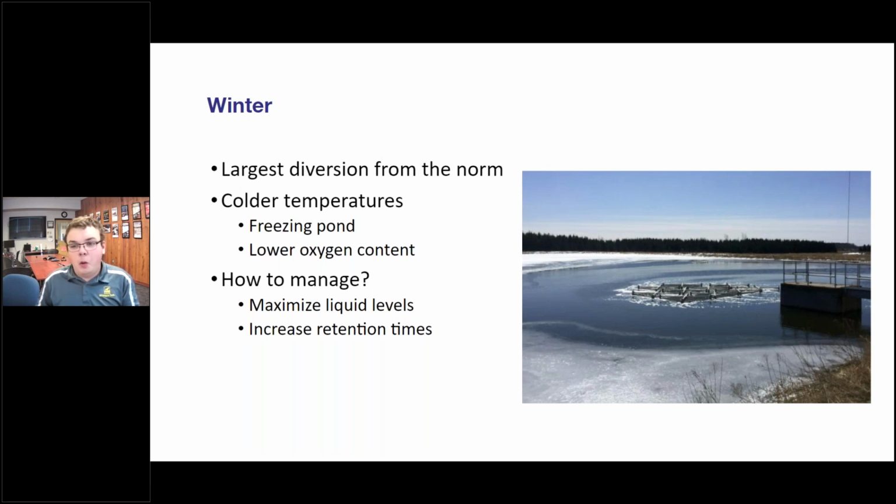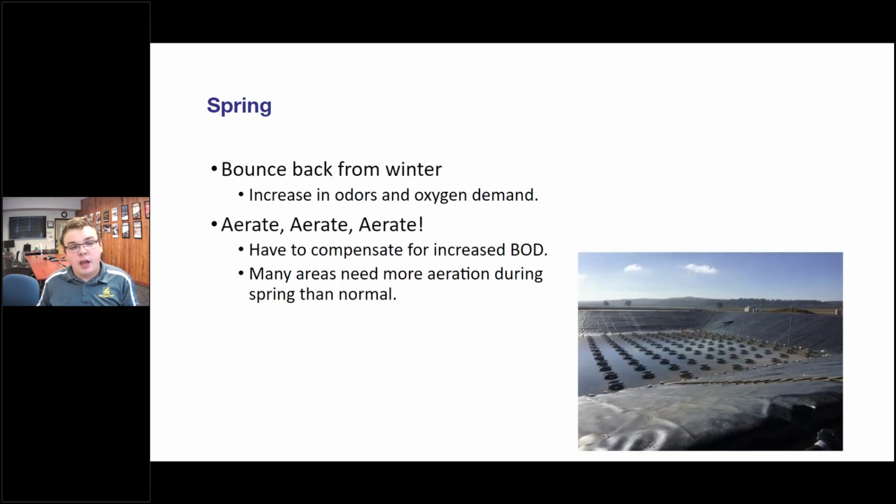Eventually, once spring hits, you're going to have this huge bounce back from wintertime. You're going to have an increase in odors and an increase in oxygen demand, because all of this waste that's been sitting in pretty anaerobic conditions is now getting exposed to oxygen and getting into more of your aerobic processes, and you're going to have to compensate for this increase in demand. A lot of systems have to put in aeration to help compensate for this, especially during that winter to spring transition.